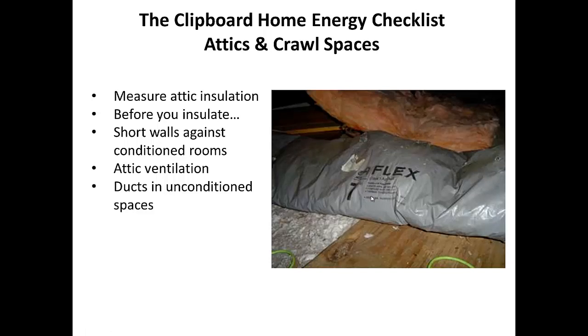Another thing to look for is the ductwork in your attic space where it's been trampled on over time. Somebody got up there, a contractor or a homeowner, and stepped on it. So, you know, the room that's being supplied by this flex duct is not getting its fair share of energy right now.